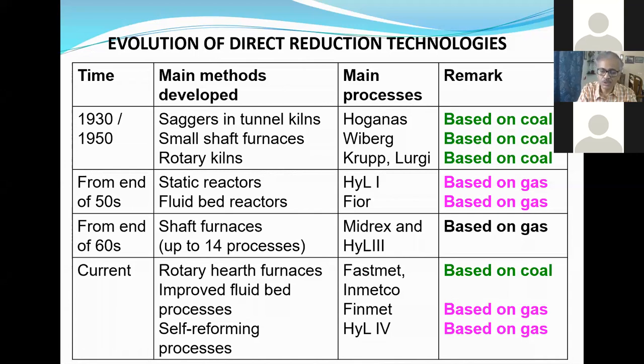But you have to put the natural gas in at a little bit higher temperature, say 1,000 degrees centigrade, and then when it goes inside, in the presence of nascent iron, the self-reforming is possible. So natural gas will get reformed inside the reduction reactor, and then CO and H2 will reduce the iron.